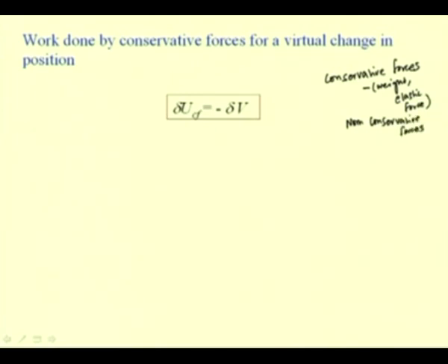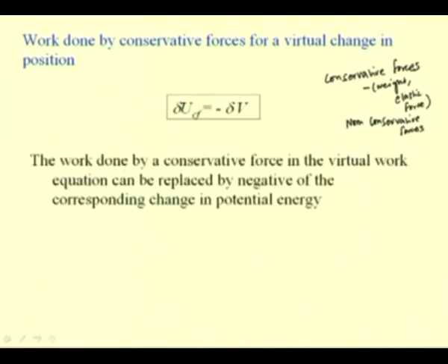In the active force diagram, we can remove these conservative forces, that is the weight and the elastic force, and only consider the non-conservative forces to compute the virtual work. The work done by these conservative forces can be replaced by the negative of the change in potential energy of the system for that particular virtual displacement. So, we say that the work done by the conservative force in the virtual work equation can be replaced by the negative of the corresponding change in the potential energy.